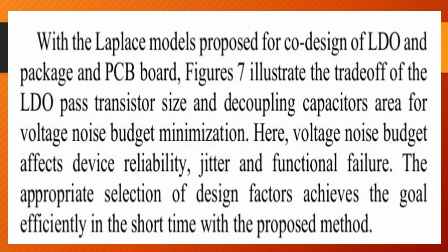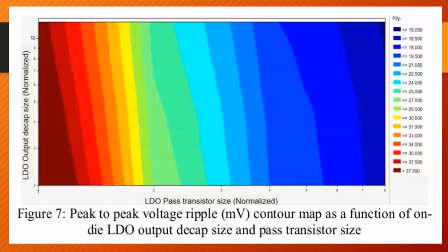Here, voltage noise budget affects device reliability, jitter, and functional failure. The appropriate selection of design factors achieves the goal effectively in a short time with the proposed method. Figure 7 peak to peak voltage ripple contour map as a function of 1 by LDO output decap size and pass transistor size.